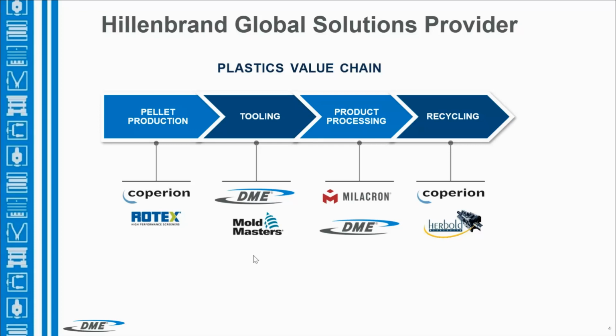Then into the tooling side, the advancements that we're seeing in the tooling are jumping, but we have an industry leader in our hot runner system that's pushing the limits of what we can do and what we can't do with these new materials, as well as all the new tooling components that are brought to the table so we can mold undercuts faster, cleaner, so we can process these exotic materials at high temperatures.